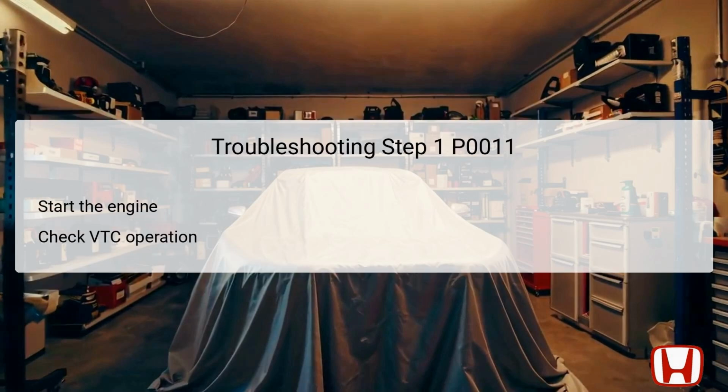The first step in troubleshooting DTC P0011 is to start the engine and observe the VTC's operation. Begin by listening for any unusual noises that could indicate a malfunctioning VTC system.